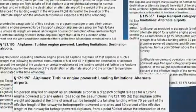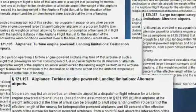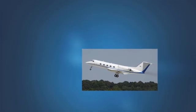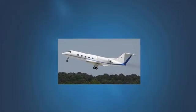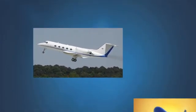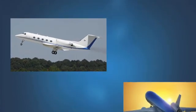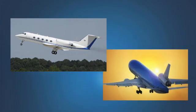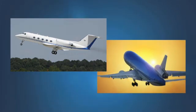This requirement does not apply to Part 91 operators, but voluntary adherence to these rules is encouraged. These operating rules impose a limitation on takeoff weight, such that you do not plan to arrive at your destination or alternate airport at a weight that will not allow you to meet the landing distance requirement specified in the operating rules. Therefore, any planning intended to demonstrate compliance with these rules must occur prior to takeoff, or as a condition of dispatch, for those operators subject to dispatch requirements.